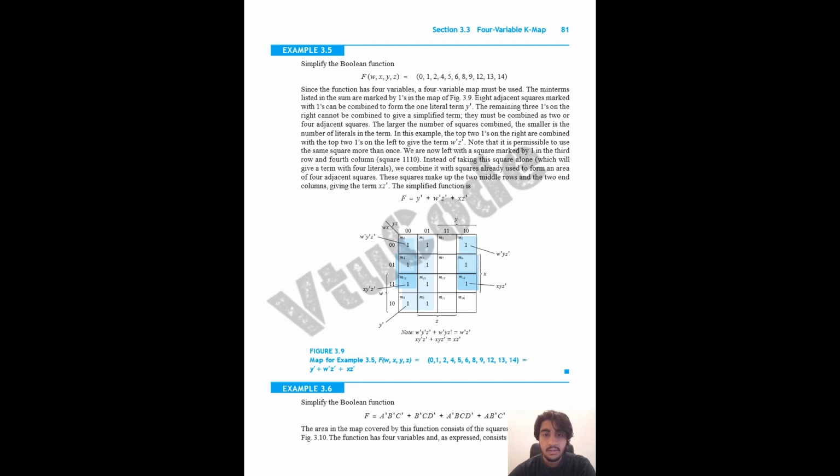Now, an interesting point to note is that we have gray coding at the position here and the position here. In a 3 variable K-map, we have gray coding only at this place and not here because we had a single variable here, but we have 2 variables here as well as here. So we have gray coding here, that is 1 0 goes to the 4th position and 1 1 to the 3rd position. Similarly here it gets reversed, 1 0 here and 1 1 here. Now after plotting all these and filling the remaining with zeros, note we are only discussing SOP